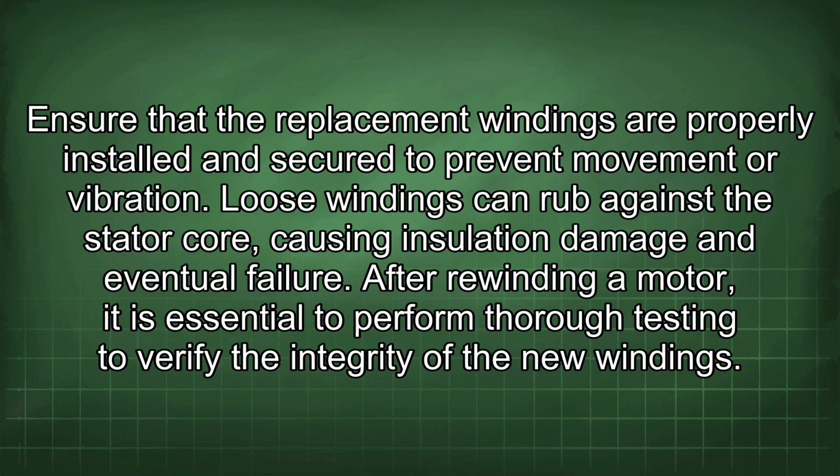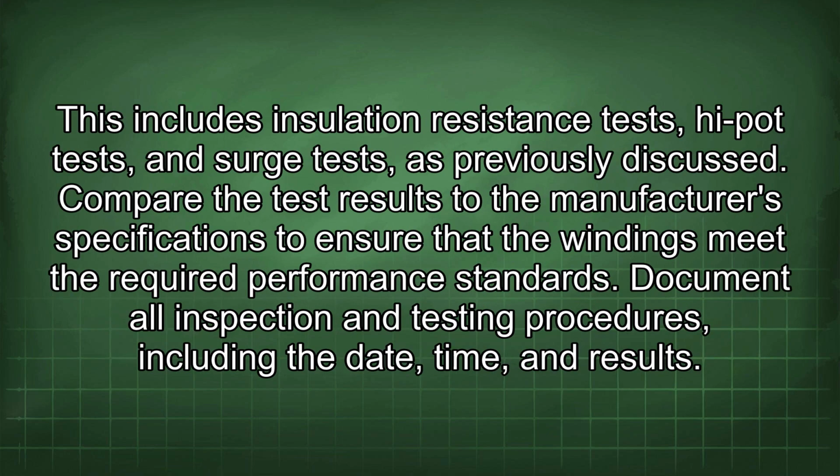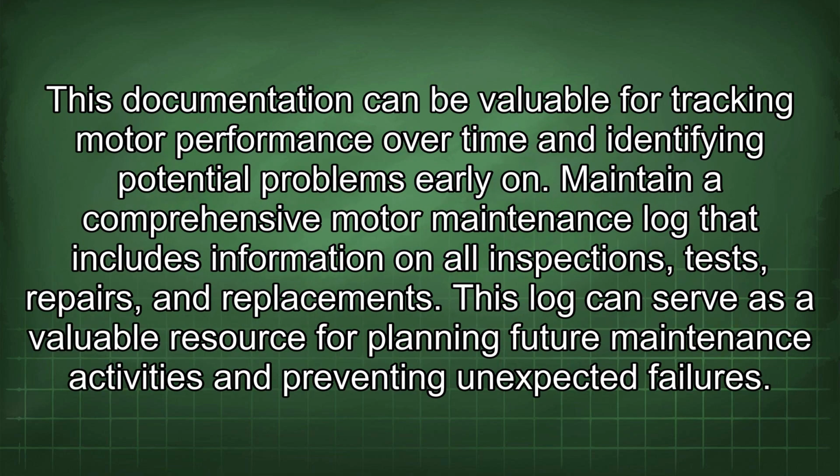After rewinding a motor, it is essential to perform thorough testing to verify the integrity of the new windings. This includes insulation resistance tests, high-pot tests, and surge tests, as previously discussed. Compare the test results to the manufacturer's specifications to ensure that the windings meet the required performance standards. Document all inspection and testing procedures, including the date, time, and results. This documentation can be valuable for tracking motor performance over time and identifying potential problems early on.